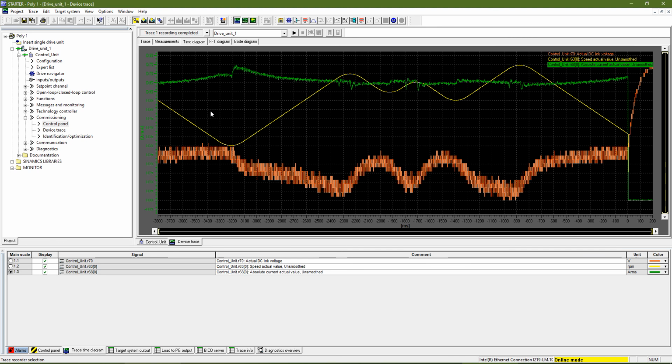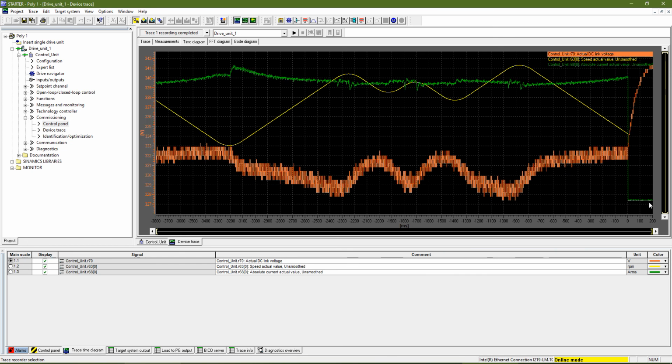And then you can see here absolute current varies a little bit, right? Again, I don't have a whole lot of inertia here, but it's just some info to look at and hopefully get a good troubleshoot of what's going on. Oh, and actually, you know what? Here, we can see the DC bus right after the fault occurs. DC bus starts to increase, basically telling me that the transformer feeding this little demo unit is a bit too small. So some of that time after the fault may be useful to you. And that's really it. That's all there is to it.